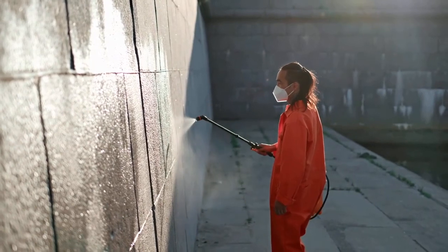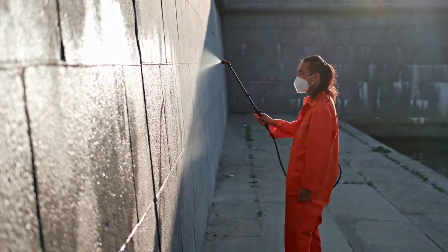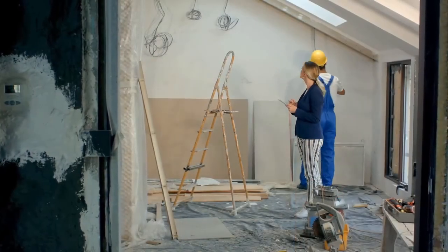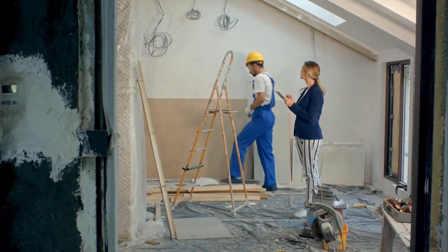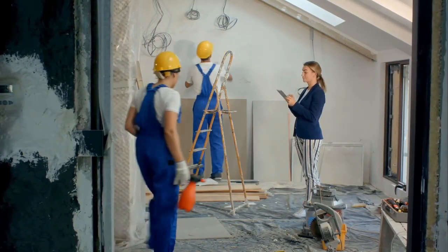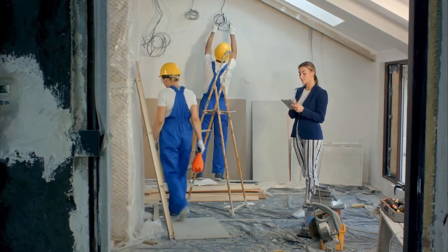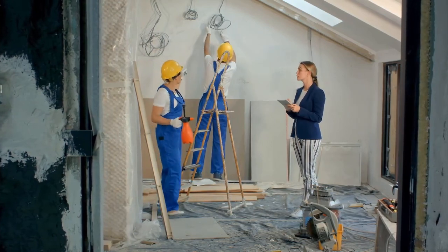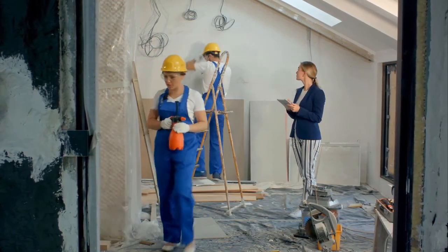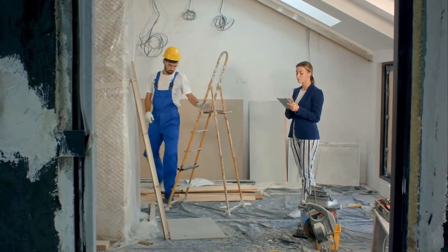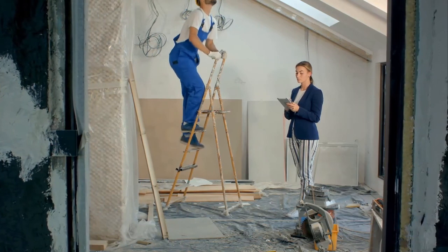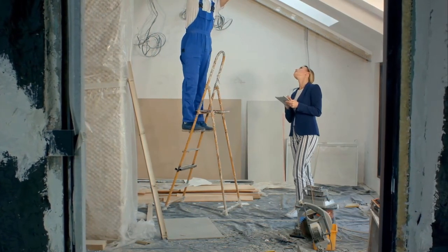The next step is to repair damage. If we find any damage on the plaster surface, somewhere breaking, somewhere undulation, or the flatness or level or line is not right, we need to repair it. Fill large cracks or holes with white cement mortar. Then check the moisture level. This is the most important part, because as per IS it is always 12%. If the moisture content is more than 12%, we cannot start the painting work or the wall putty work. So you need to check the moisture level.